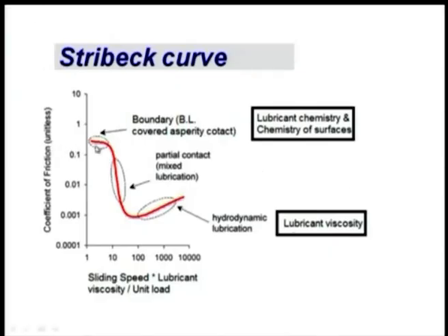Here we are able to see a broken line, or there is no continuity from 0 to some point. That is indicated when the relative velocity is 0, then this system will not act as a tribo system. That means we cannot plot these results with 0 velocity. That is why there is a discontinuity. Coefficient of friction here does not mean the static coefficient of friction, we are talking about the kinetic coefficient of friction. And coefficient of friction is unitless. It is a force divided by force.